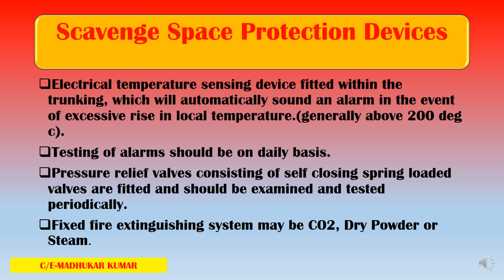The fixed fire extinguishing system, CO2, dry powder or steam, whichever is provided, must be charged, and the complete operating instructions must be in position. Every person in the engine room must be familiar with this fire extinguishing medium, the procedures and the guidelines.